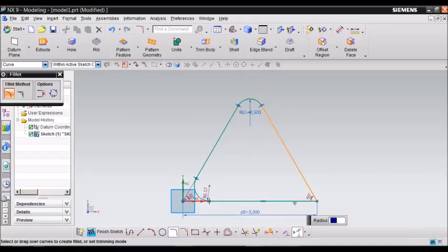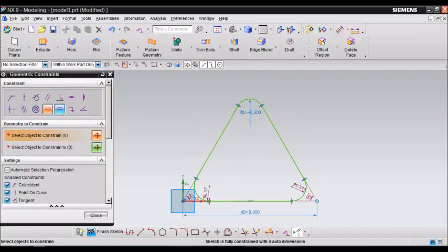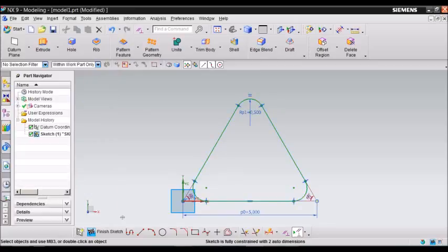We're going just to assume the radius that is given by the software, and then we're going to use an equal radius constraint. So we select this radius and then this one. We select now this radius and then this radius and close it.